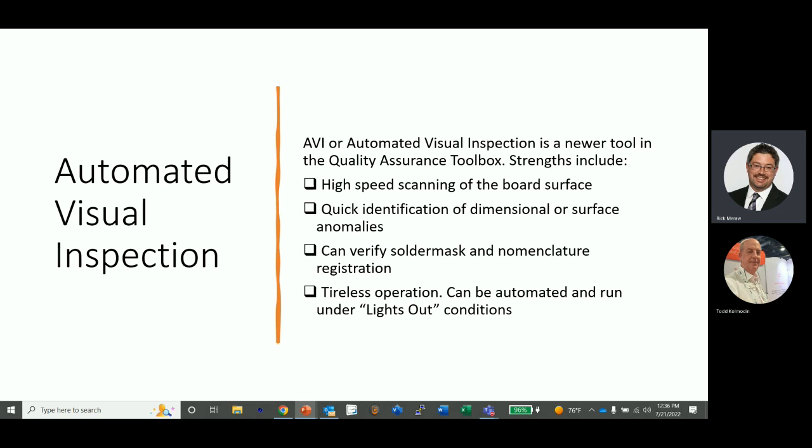It's the same sort of thing, except the CAD is a little bit more complex because you have to put everything in there. Of course, under CAD images, there's not a lot of CAD products out there that are using different colors, because with solder mask, you can have red mask, green mask. On the surface finish, you can have gold, you can have HASL, you can have Entek. There's many different colors, and you can have a mixture, gold fingers. You can have different kinds of silk screen, yellow, red, whatever the buyer is looking for on their printed circuit board. So all this is accounted for.